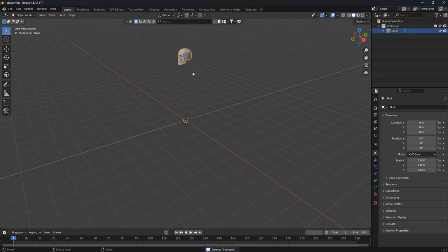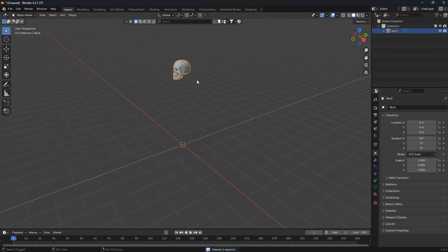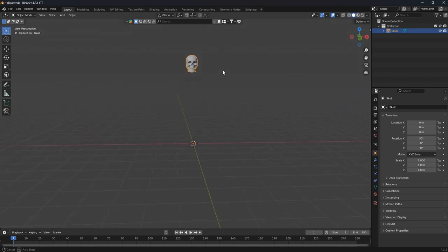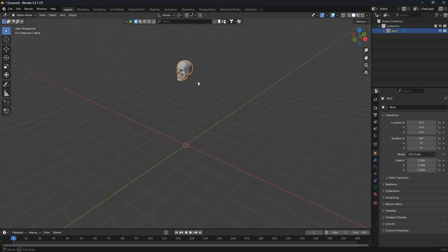Okay, just leave the scope. Right now, as far as you can see, it's not in the world center. So it's better for you to bring your model to the world center. Otherwise, if you export this model and bring it to some other software, it will probably float away. You cannot see that in your viewport. So let's bring this one back to the world center.